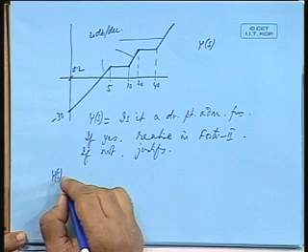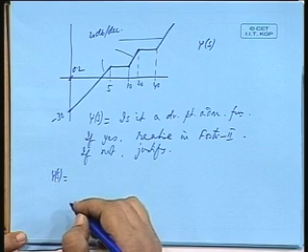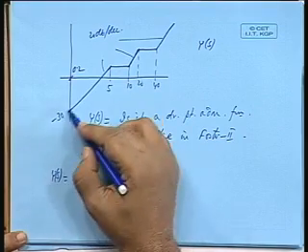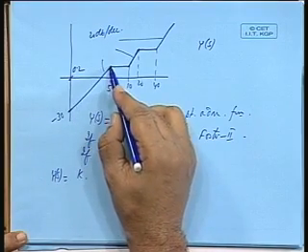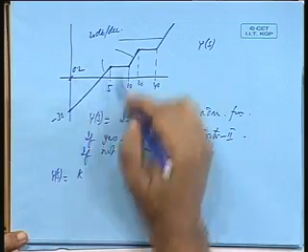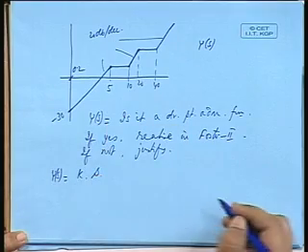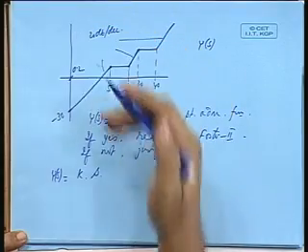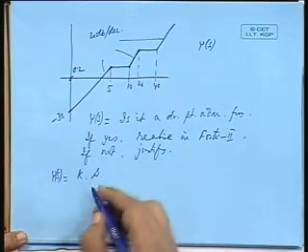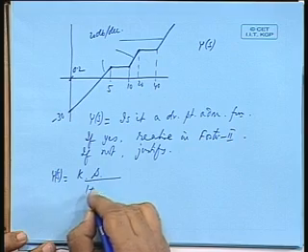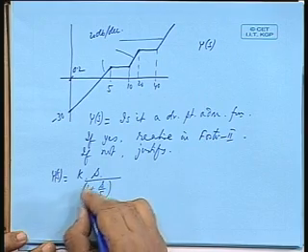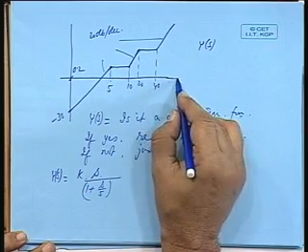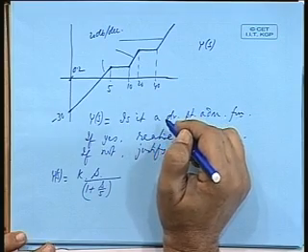Let us write Y(s), the nature of Y(s). It will be k times, there is a function that is going up. So, the factor corresponding to that is s. Then the 20 dB per decade slope is made horizontal, that means there is an addition of a term 1 plus s by 5. Okay. This is in radians per second. Then 1 plus s by 5.